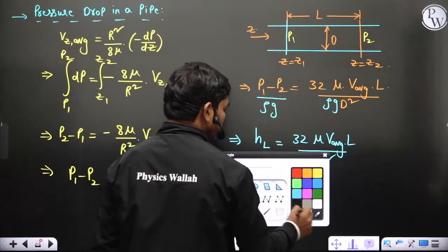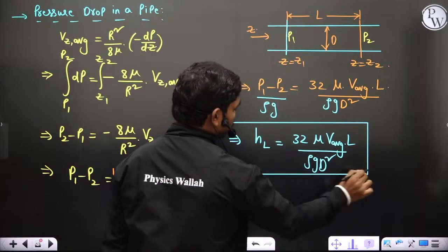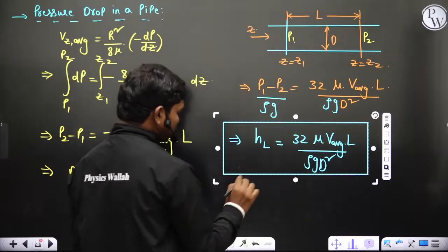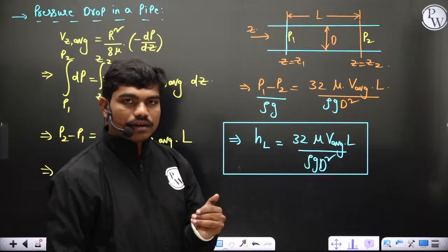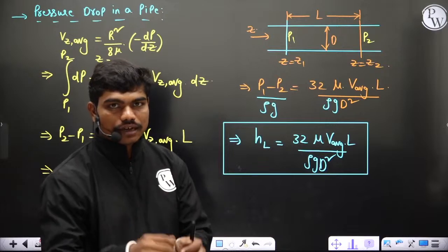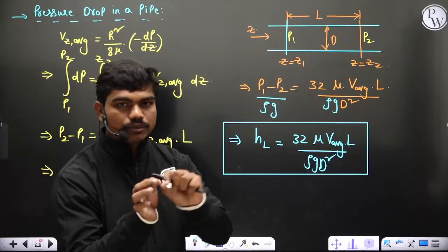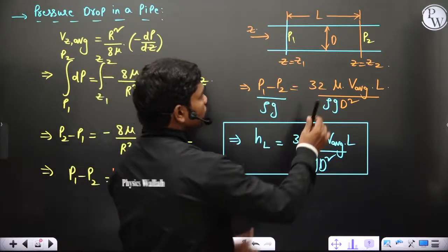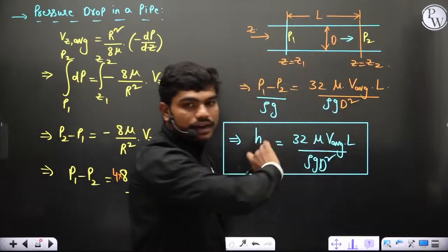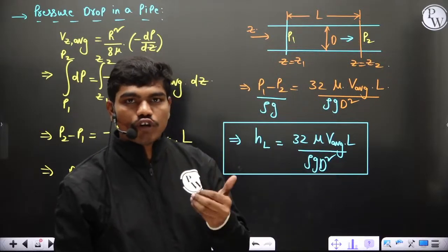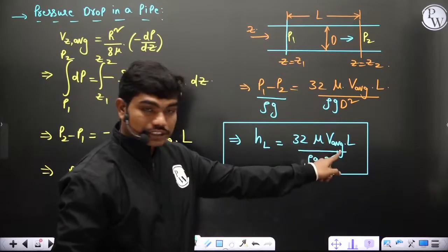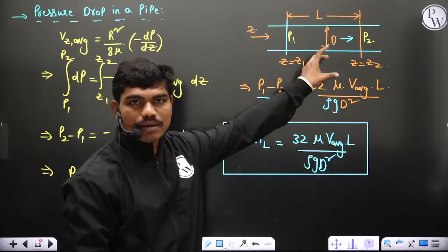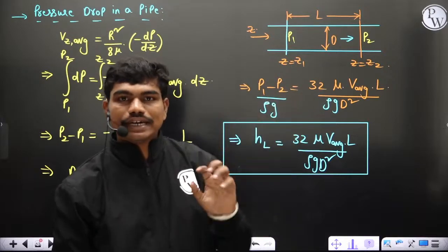Okay, so this is what we have, and you can understand one more thing here. Normally, instead of calculating velocity, if you go for applications, the main thing that is focused on is the discharge between 2 points. That means what is the volume of fluid I should send in this pipeline. For a given amount of volume, you can decide the pipe diameter and velocities. So instead of writing velocity here, because velocity changes with respect to pipe diameter, it's always suggestible to write discharge